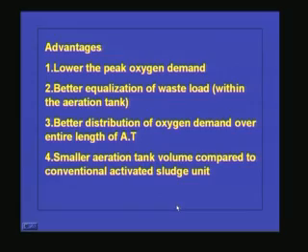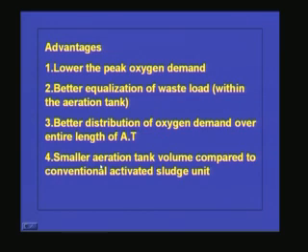Here biodegradation as well as dilution take place, and the concentration gradient is high, then reduces, then again increases and reduces. So you get high and low concentration gradients, which increases the degradation efficiency, and moreover the volume of waste present in the tank is effective in dilution. Because of these reasons, the volume required in a tapered aeration system is less than in the conventional aeration system.